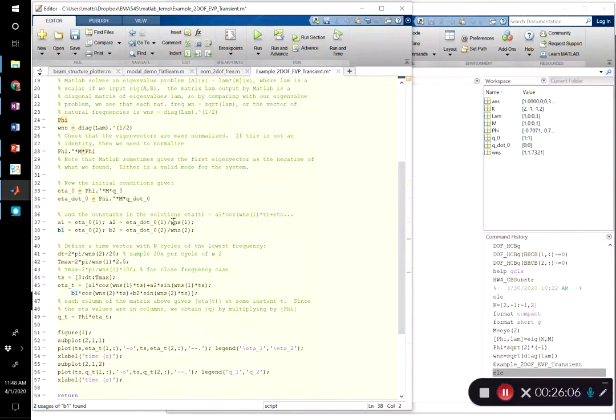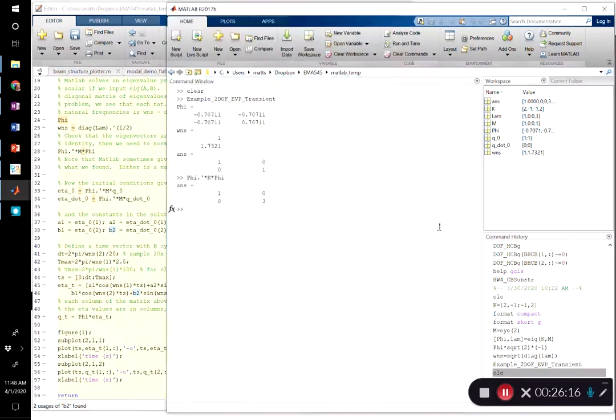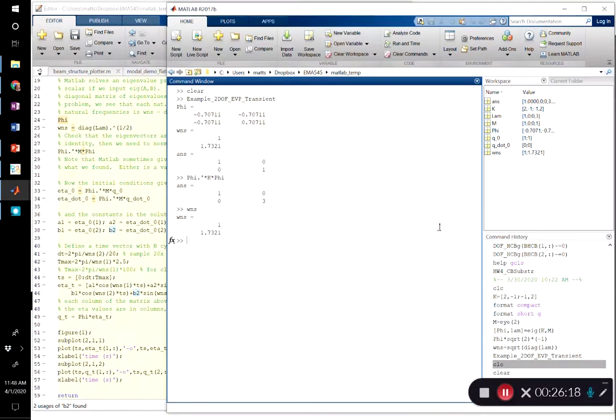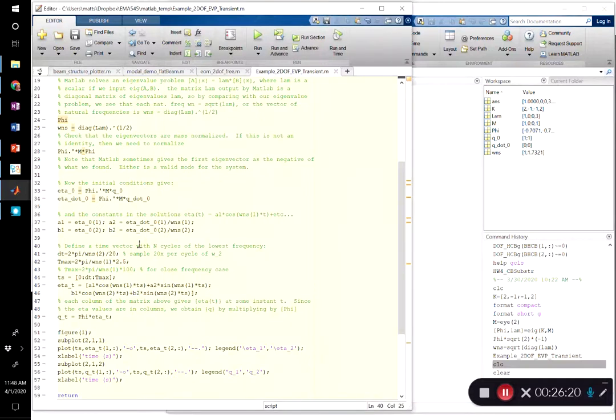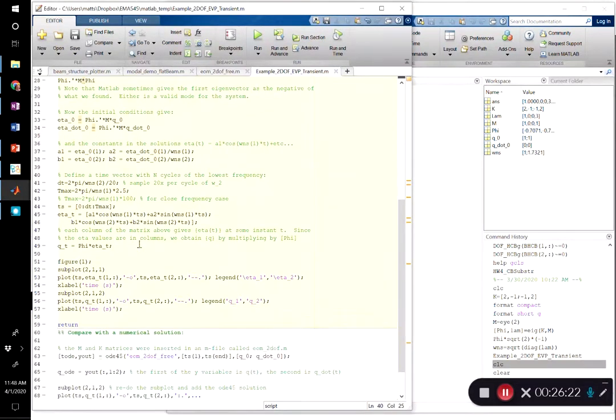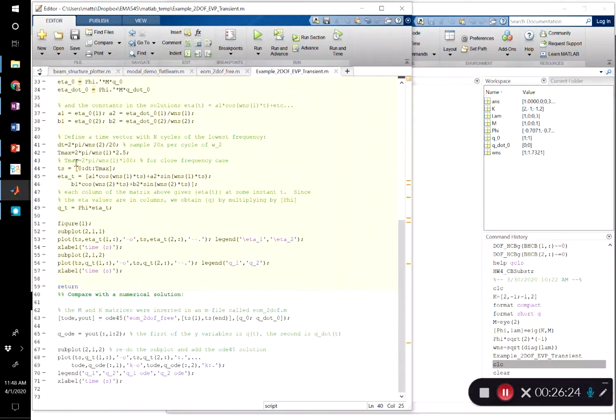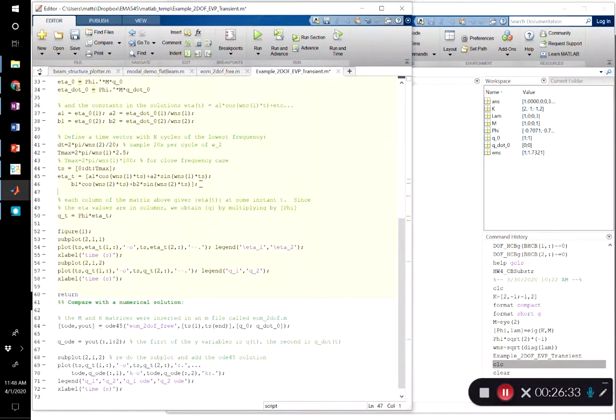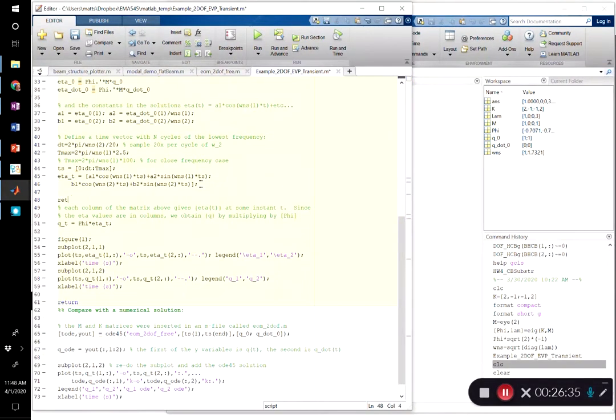And the velocities, we'd end up getting the coefficients on the sine terms are the initial velocities divided by the respective natural frequencies. So omega n is a vector that has both of those natural frequencies in it. Alright, so I define a time vector, and now I've constructed a matrix eta of t. Let's just look at what's happened up until here.